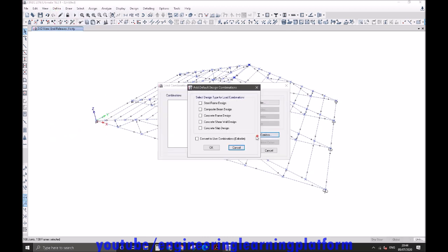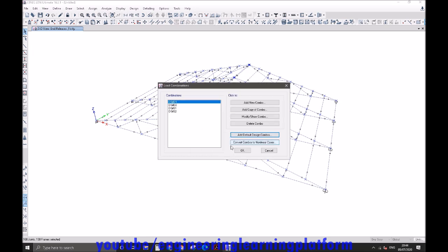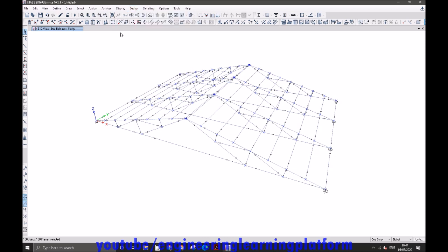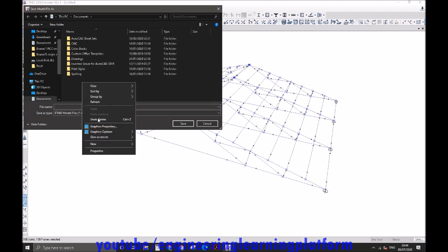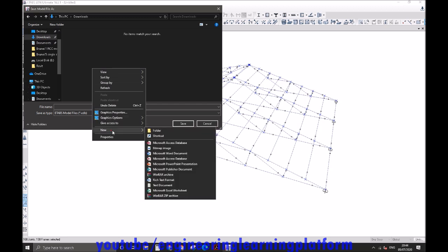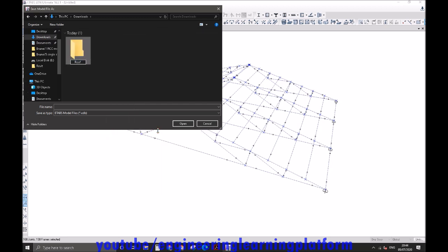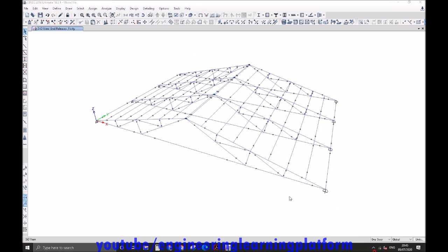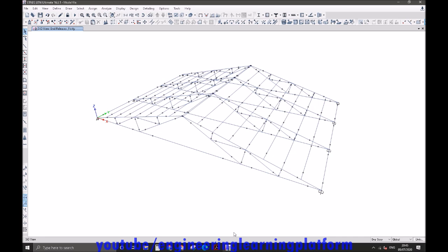However, in some places it is important to apply the wind load on the truss members here. I'll be loading the default combinations for AISC LRFD and adding them in the design part. They are already added, while the rest two were deflection combinations, which you can always check by L by 240. That is permitted by the code. L by 240, that is, the span of the truss here is 90 feet, divided by 240 will give you the allowable deflection in feet. You can always multiply it by 12 to get it in inches, and check it on the combinations that are service, live plus dead.